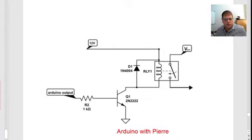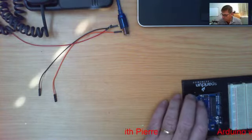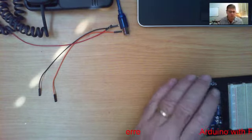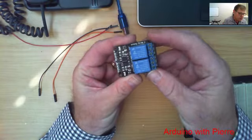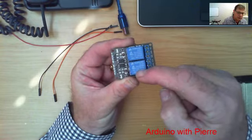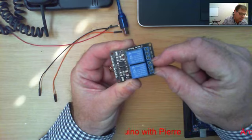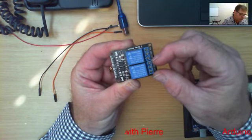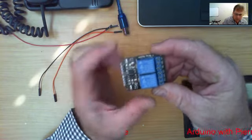Now with the Arduino we will have many different types of relay boards that we can use, and I can show you here. Here's a relay board that's got 2 relays in it. So here's the switching side of that relay, where it will actually switch our high current load, and on this side we will couple our Arduino.